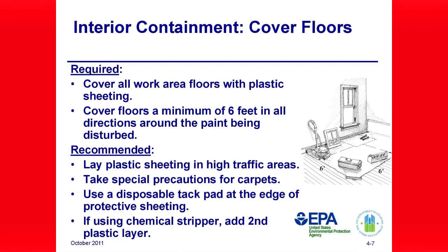A second, smaller layer of protective sheathing should be used with chemical strippers. The second layer should be taped to the top of the first layer. When the second layer is immediately removed from the work area, it should be captured and put into a waste bin.